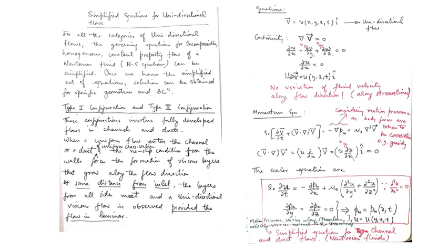basically implies that the flow cannot be turbulent, because you will learn in the last unit that all turbulent flows tend to be multidirectional. They are never unidirectional. The velocity has all three components in space. So the basic idea of a unidirectional flow is not compatible with turbulent flows. It's only compatible with laminar flows. So keep this in mind, and I will not be mentioning it again and again.